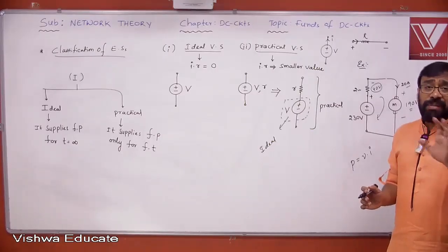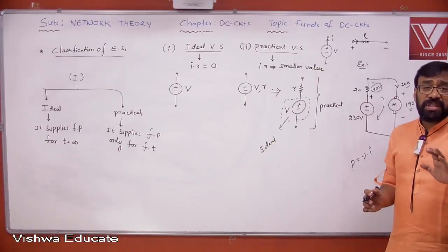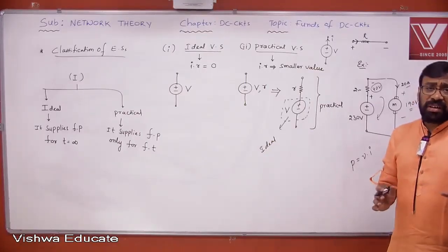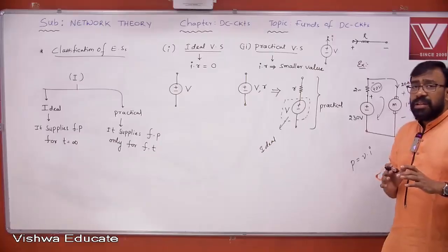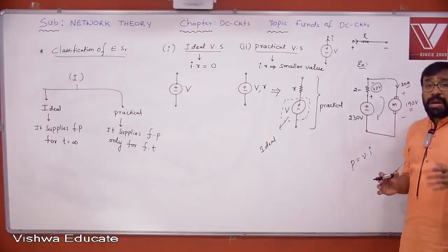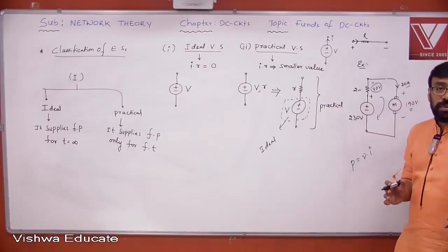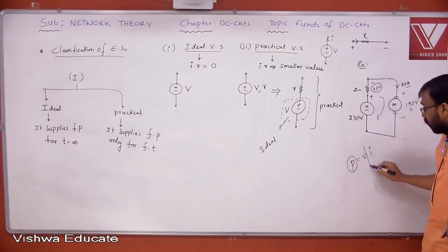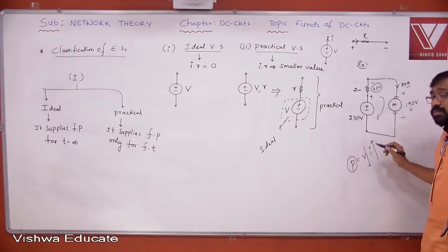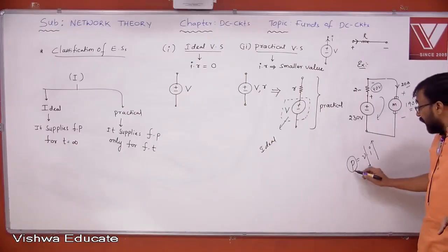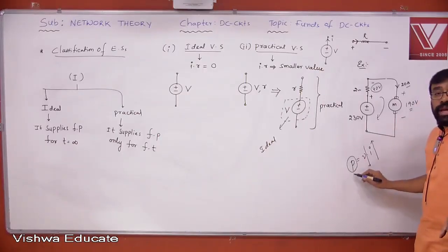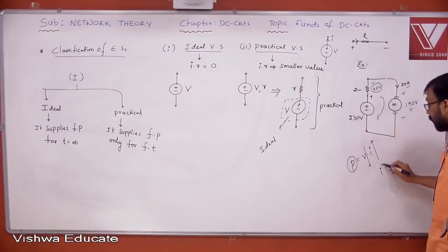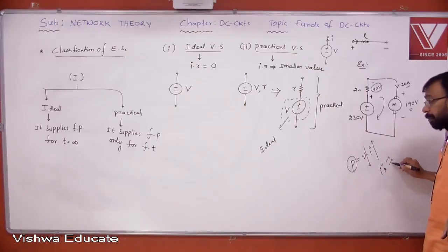See, don't tell me with respect to the speed or the efficiency or any other thing. I'm not talking about torque or power or speed. I'm talking about the safety of the motor. Look at this. To maintain the same power, at low voltage, the motor draws high current. Then what will happen? I square R dissipation is very high.